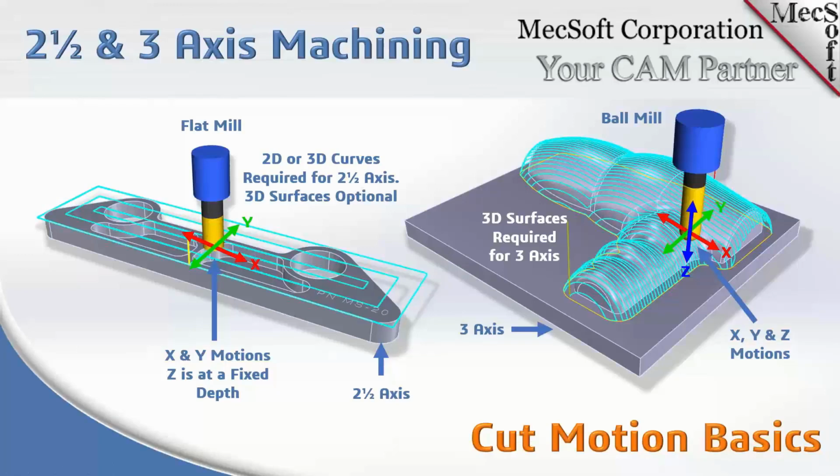Now, let's talk a little bit about the difference between 2.5 axis and 3 axis. Basically, it's defined in how the tool moves. If you look on the left side, you'll see that we have a red arrow X and a green arrow Y. The tool can move in these 2 axes simultaneously, but it's fixed in its Z axis.